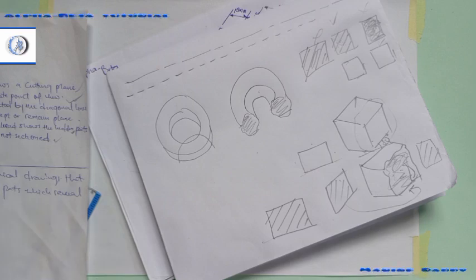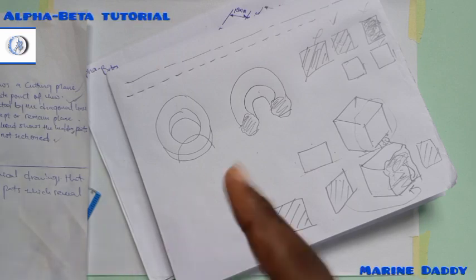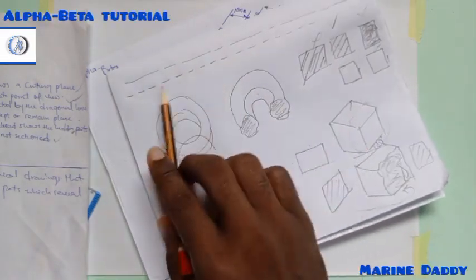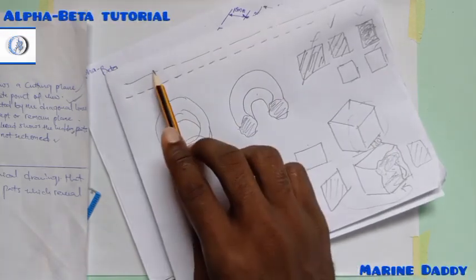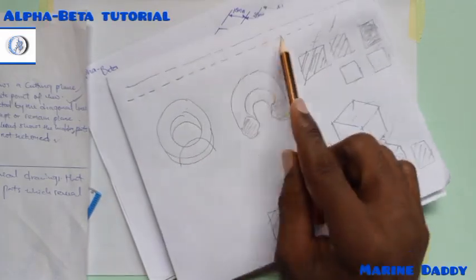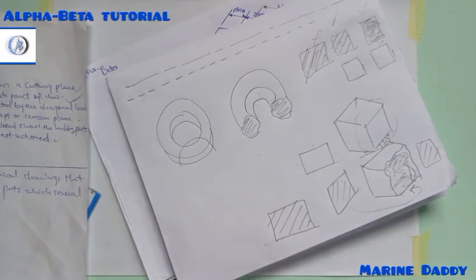Another rule you need to take into consideration is broken lines. You don't use broken lines in sectioning. You only use them in orthographic projection. Remember, what I was trying to explain previously when I brought up imaginary lines, I said that broken lines are used to show hidden details of a diagram. But sectioning is contradicting it, right? Because sectioning is revealing the hidden details, right? So why will you reveal hidden details and still put broken lines to it?